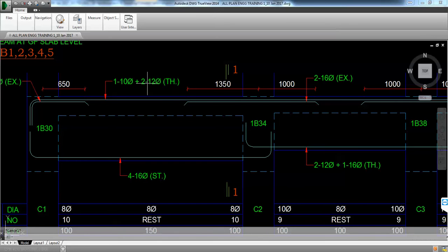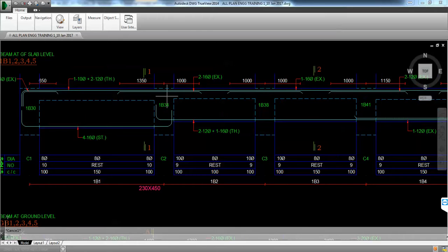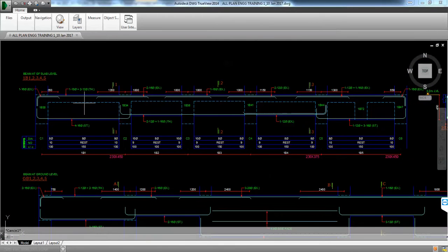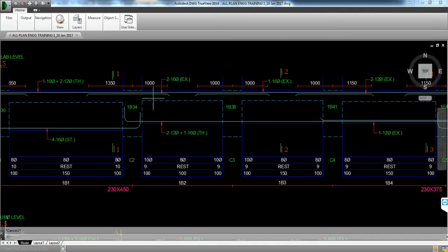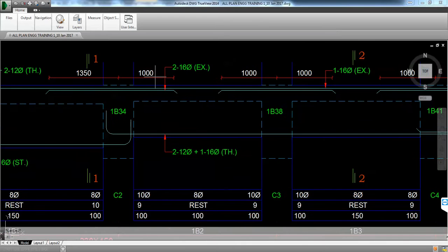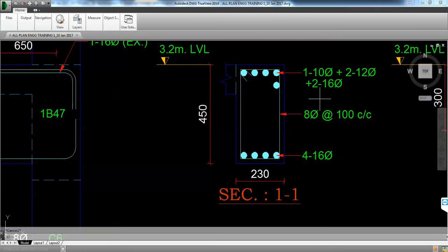For the full length. Yes, but for the intermediate I'm interested now. The 2 phi 16. So I'm doing now this intermediate bar. At the end I will do the full bar. So for this is 2 phi 16, I see, which is placed where? In the drawing it's missing. Is this lower? Which is placed 18 here and 18 here. Oh, okay, interesting.